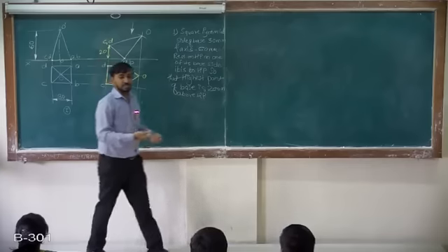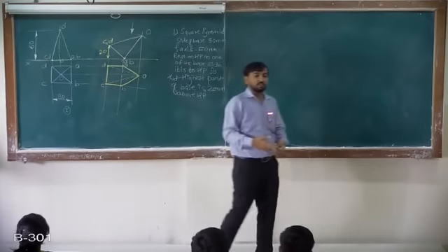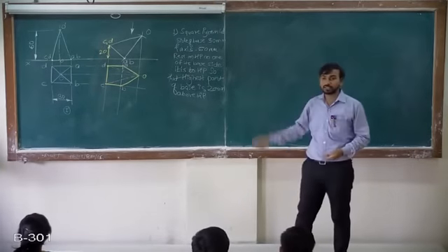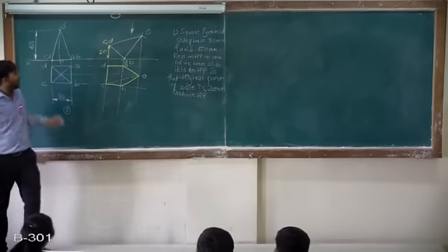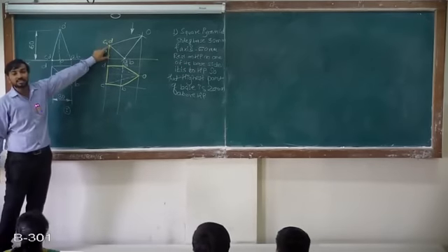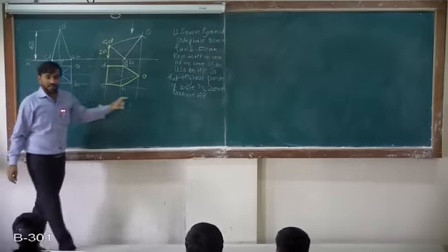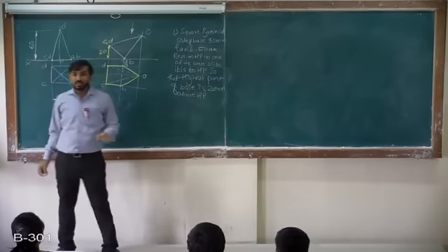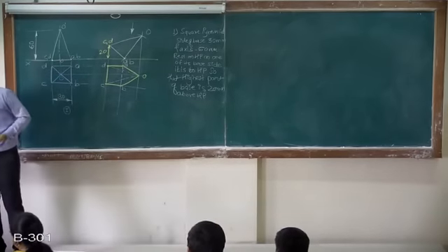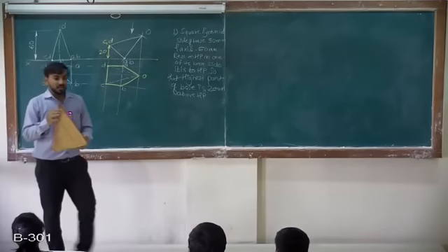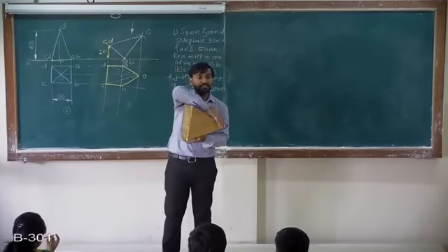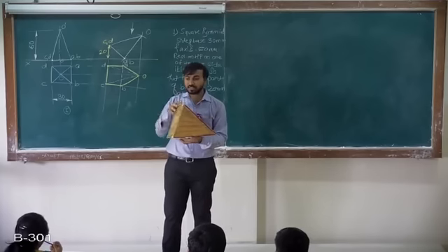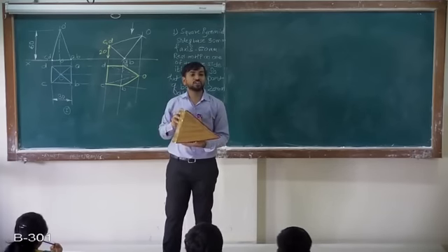Because it's logical, when the angle is given in the corresponding view, we are not going to see the corresponding slant edges. Now this is the condition when the locus for this point CD is given. Got it? Any doubt in this? Now we'll see the next condition, apex at minima. We saw this is the condition when apex is at minima, that means it is resting on a face.